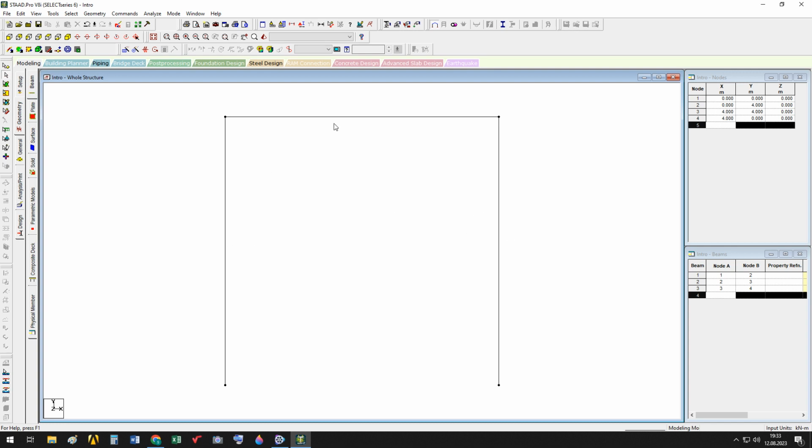You see, these are actually frames. Frame means beam, column, or beam column element. Its length is very long in comparison to its cross section dimensions. This is the property of frame members in statics. So the important thing to mention here is that beam in Staad Pro means frame.